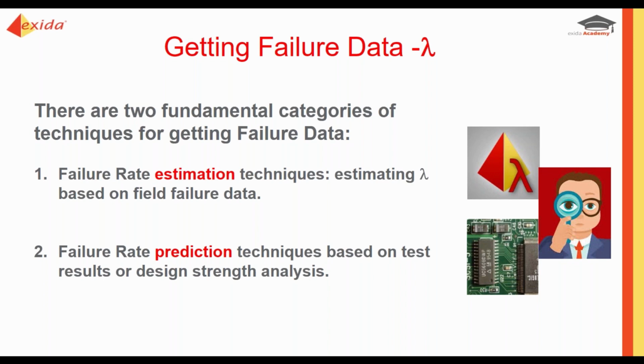We'll look at how estimation takes information, analyzes it, does its statistical analysis, and it can estimate future failure rates given historical data. The second way of getting failure rate data is from a predictive analysis, and that technique is either based on test results or a design stress strength analysis. And we're going to look at both of these in more detail.